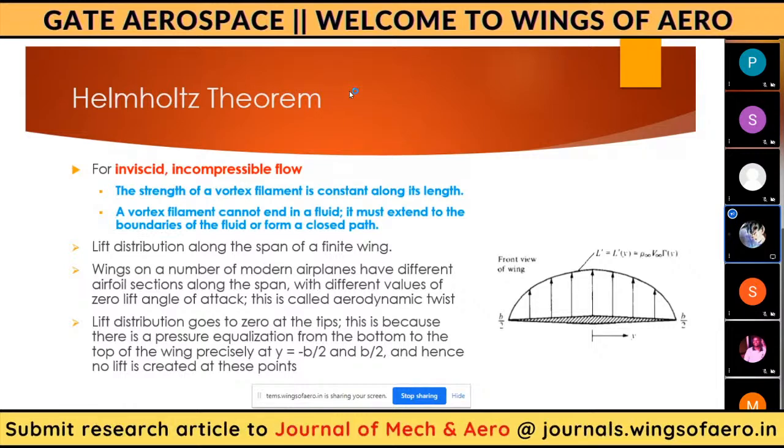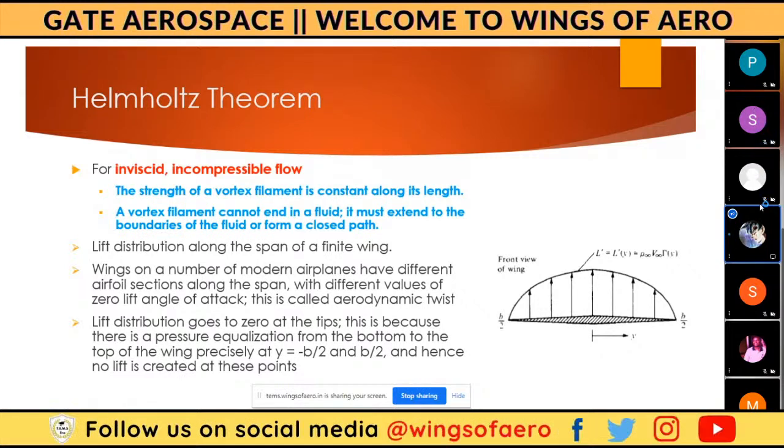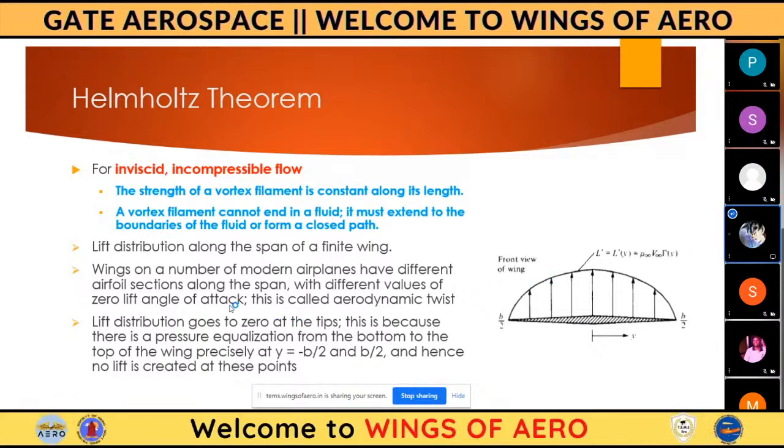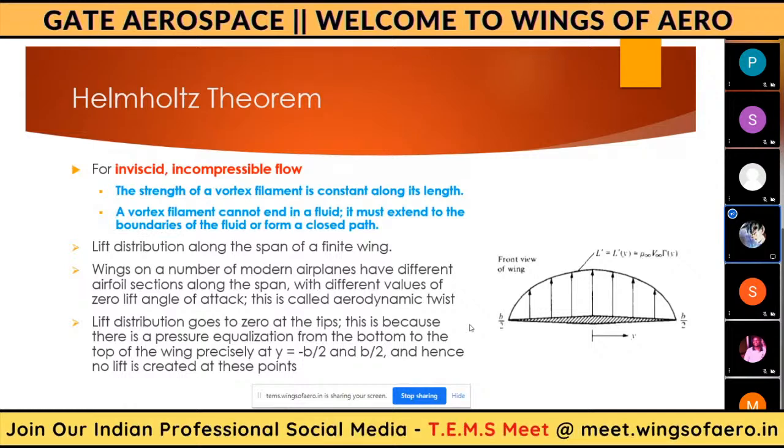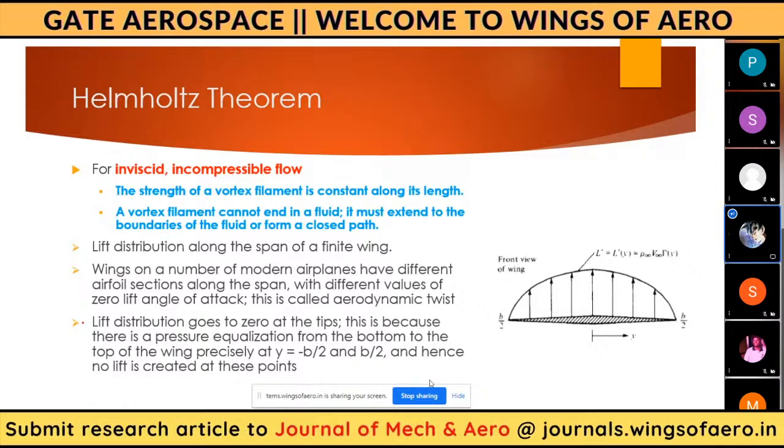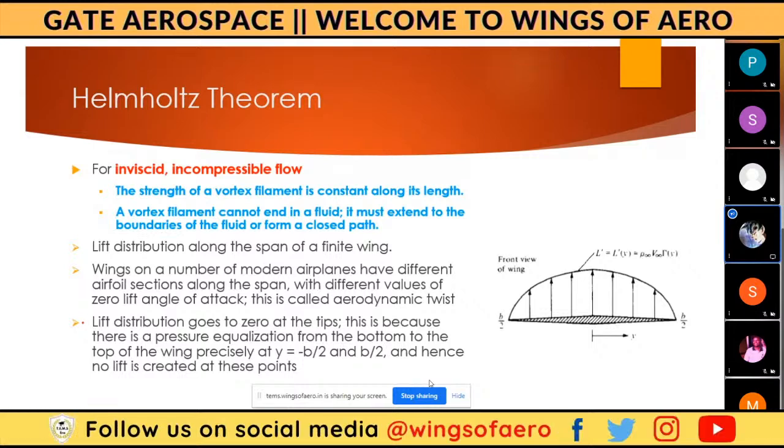For what purpose are they giving that fine mesh? After the trailing edge, there is some disturbance, or some vortices formed at the downstream of the aerofoil. In order to capture those downstream vortices or disturbance, we will mesh the region after the trailing edge very finely. I will show you some images next session, as I don't have them now.